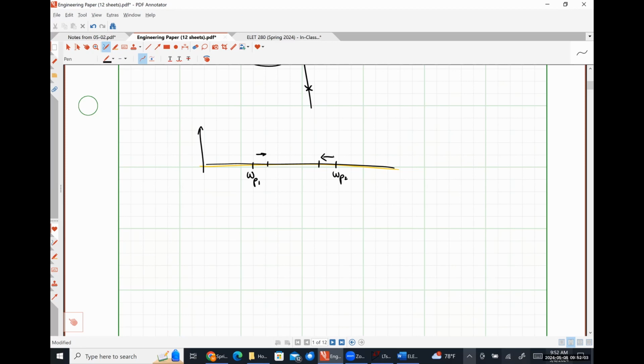The capacitance C mu, its MOSFET analog would be the capacitance CGD. So again, it's the exact same resistance, but everywhere you see R pi, treat it like an open circuit. CCS, for what it's worth, has an analog of CDB. CSB does not have an analog.